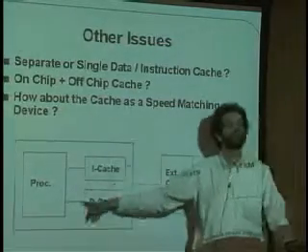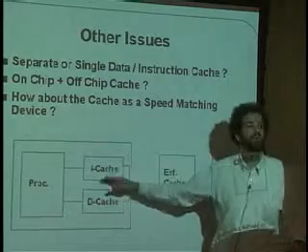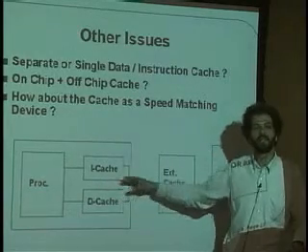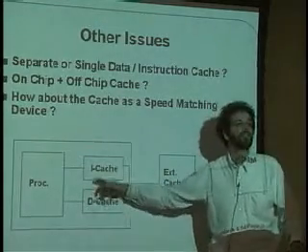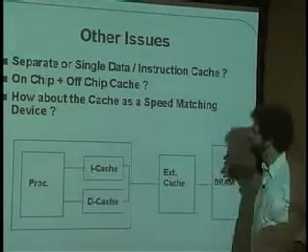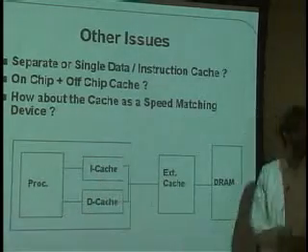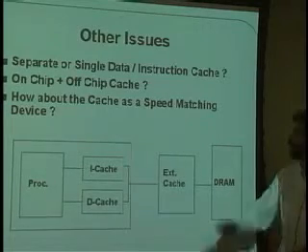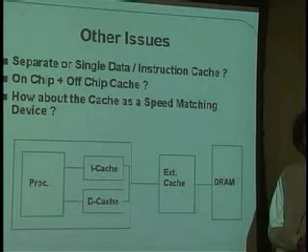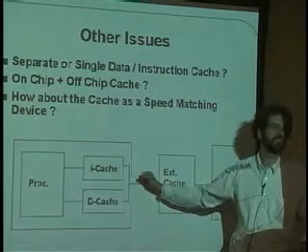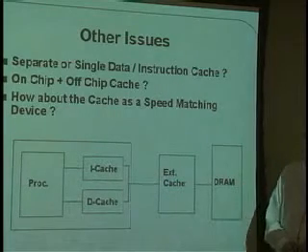Why? Because this guy can go on and do other work while we're waiting for the other words to come in. For instance, once it's got the first word of a block and it's gotten its hit, the other words of the block can come in the background while this thing hopefully is getting other cache hits and doing other work. And so we can have in parallel the filling of the cache line from here to there while this thing is going at a much faster rate and getting cache hits in the cache. Of course, if it then gets stuck in a cache miss again, it's got to go back out yet again. But now you get an idea why the folks who make processor boards are pushing so hard to get this front side bus to go faster and faster, because going off chip is just so horrendously bad when the processor is running so fast.